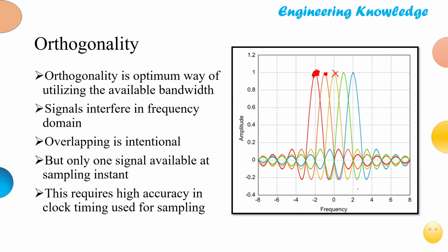So at different frequency points we have only the maximum of one. All of them are overlapping, but they are orthogonal, and we can sample one of these multiple carriers. By sending multiple carriers, we make Bs upon n smaller than the coherence bandwidth and still manage to sample and retrieve our information signal.